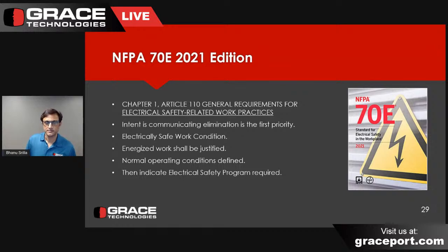So the missing link with the industry is there's a lack of electrical safety programs or compliant programs, and this is hopefully helping users clarify this whole thing: we have to have this upfront policy, right? We turn it off. We can't turn it off. We have to have justification for energized work. That was moved from Article 130, where the energized electrical work permit was, and the energized electrical work permit still is in Article 130 or Clause 4.3.